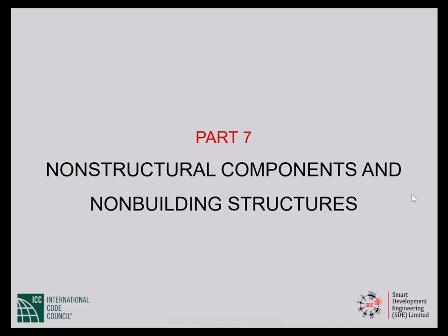Which load case or combination shall be considered for checking torsional irregularity? Torsional irregularity does not have anything to do with load combination, is it? Torsional irregularity, when you calculate the deflections. My answer will be the same. We are talking about the lateral deflections. And when we are talking about torsional irregularity, we are really talking seismic. So it is the deflections under the strength level seismic forces that are important.